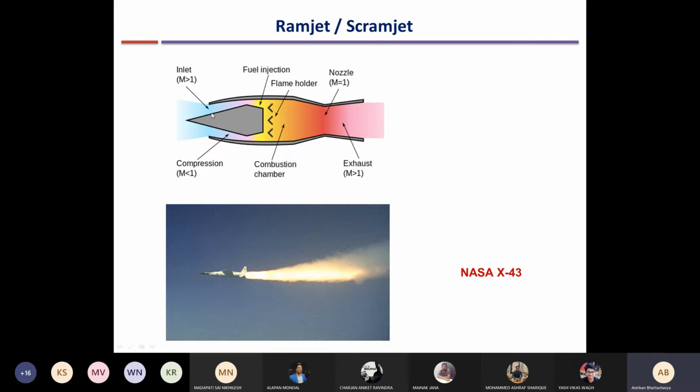So in these cases, you have a convergent divergent diffuser. The convergent part is for the supersonic speed. Convergent means the diffuser needs to be convergent, the area needs to decrease, if you are at supersonic speed.